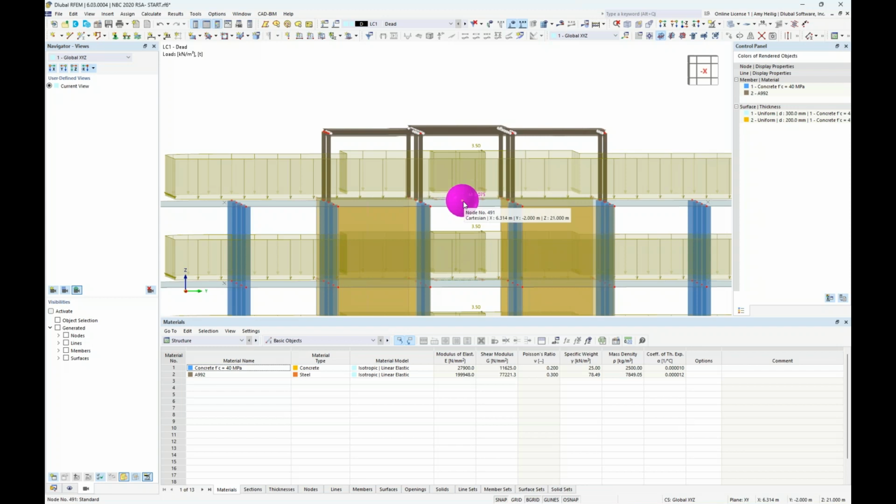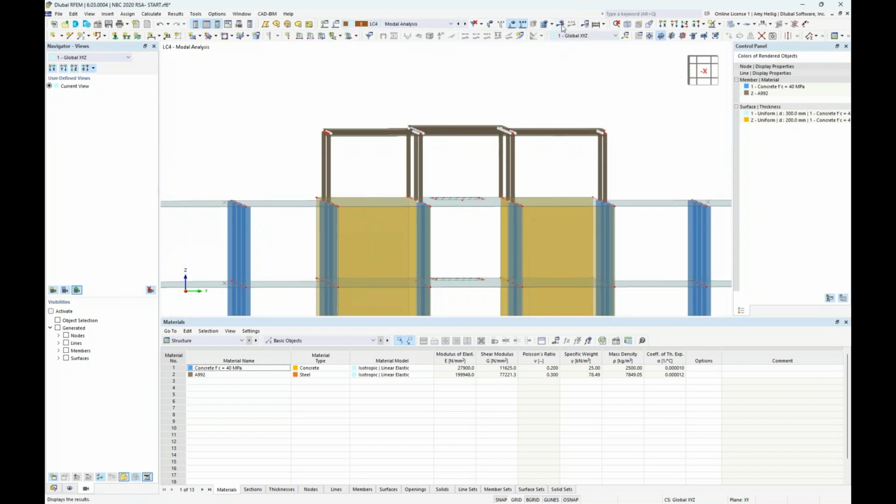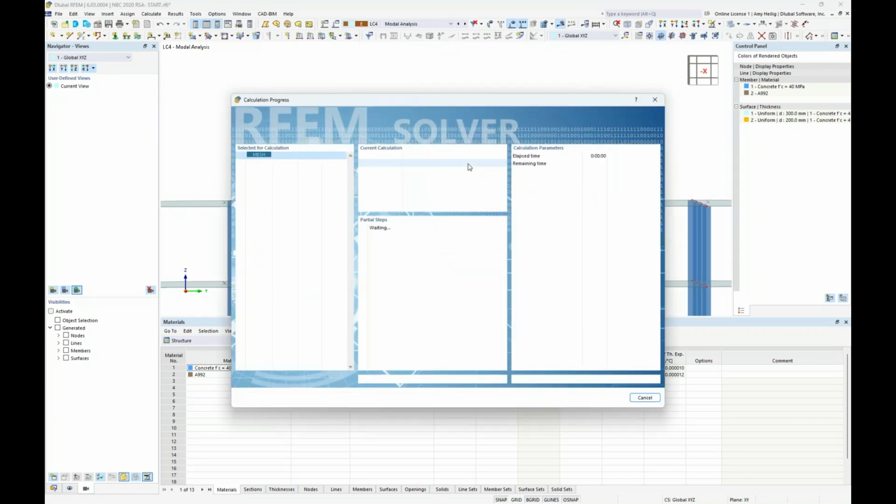of our concrete structure. So we have the ability to apply mass loading as nodal loads, as we just saw, or line loads, member loads, or surface loads to be considered further within the modal analysis directly. So we jump back down here to the modal analysis. We're going to rerun this calculation, and remember now that we are completely neglecting the masses from the steel members, but rather we have now inserted that single point mass load at the top of the concrete structure to simply redistribute the mass. And our hope is by still solving for 10 different eigenvalues that we see slightly better mass participation.